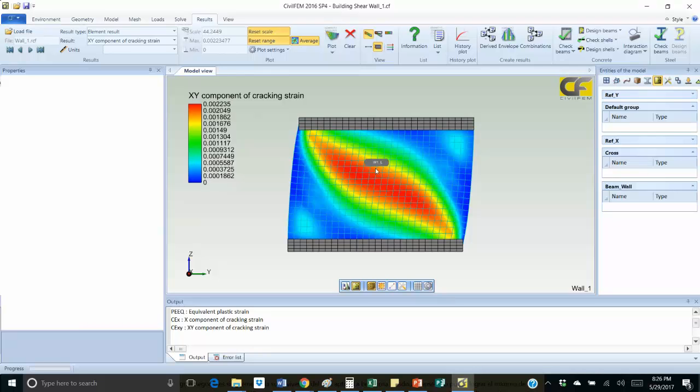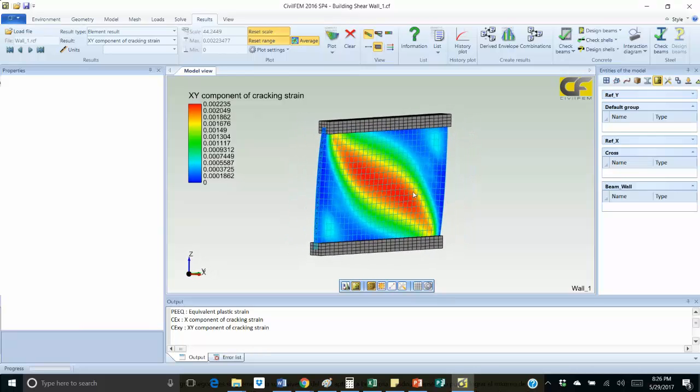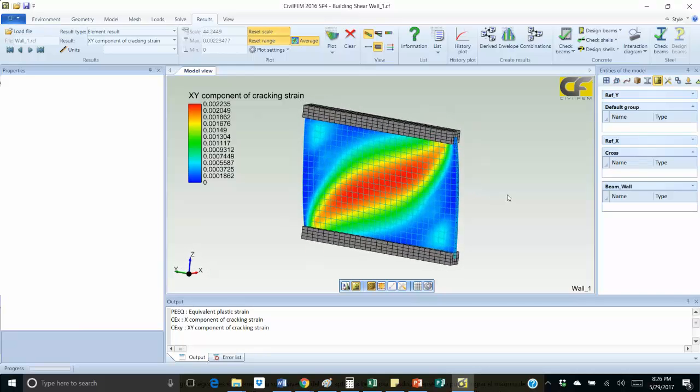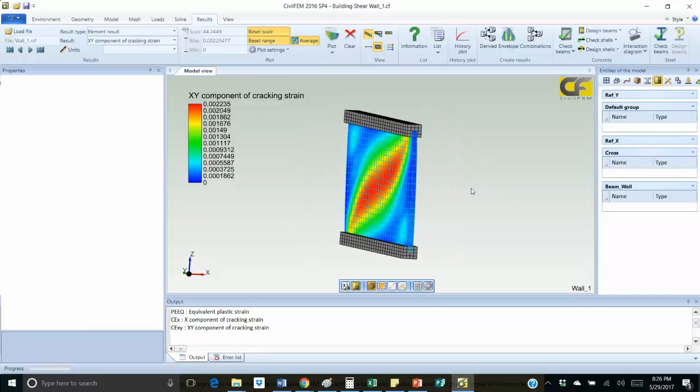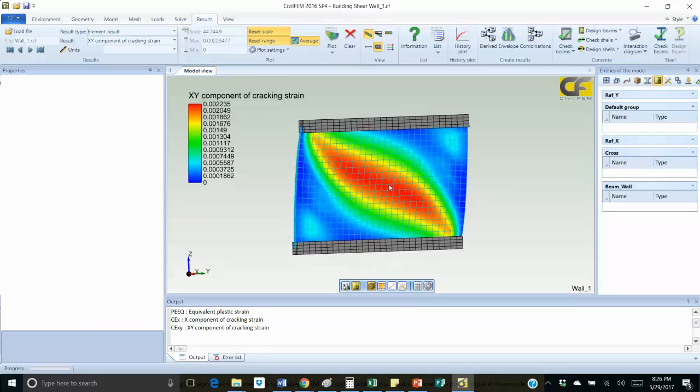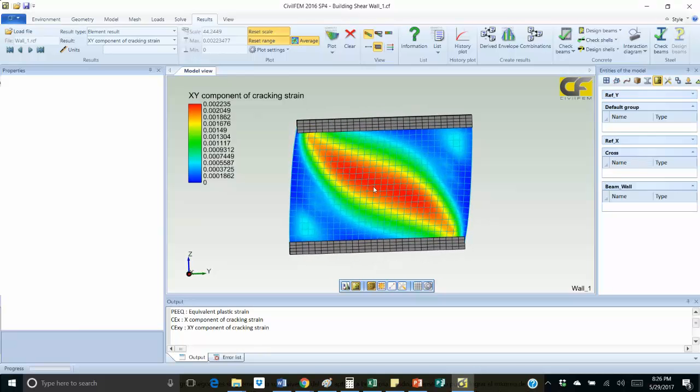Due to the high nonlinearity performance, we can use the software for calibrating real models, for making investigations, and for forensic engineering. It is a powerful tool, because automatically and very quickly we can evaluate this complex behavior, where there is concrete cracking, taking into consideration the bonding of the steel, the interaction of the bars, and all of that for the cracking analysis.